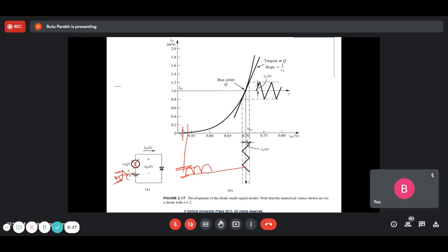So that it can rectify this weak signal, which is very little, first thing is you have to make the diode on. How do you make the diode on? By giving a DC value, a DC component. That is, you make this 0.7 volt. Then it is already operating, and to that you superimpose your little sine wave. At 0.7 volt it is already on. Onto this signal, we will superimpose your little varying sine wave.